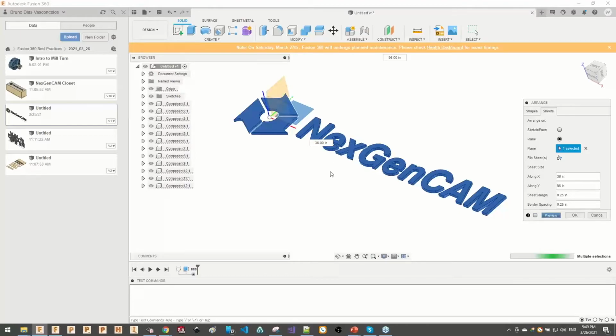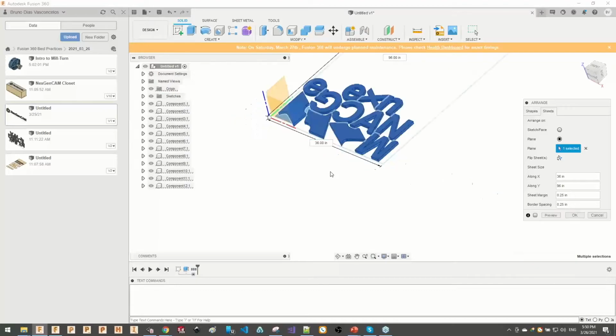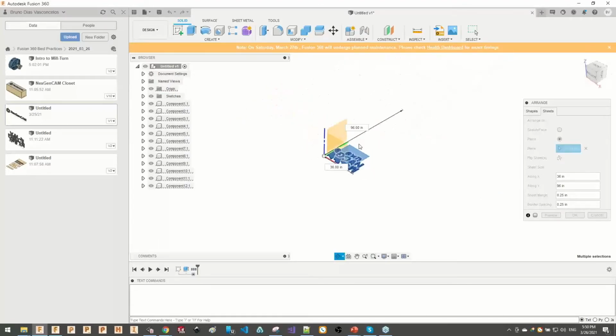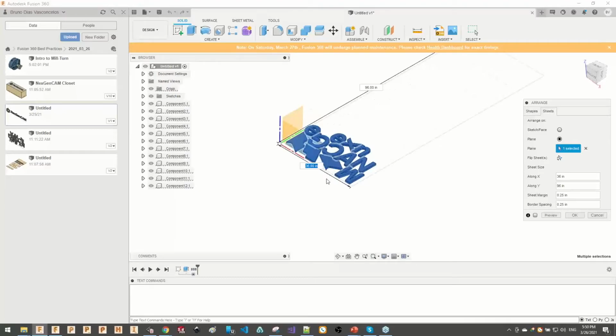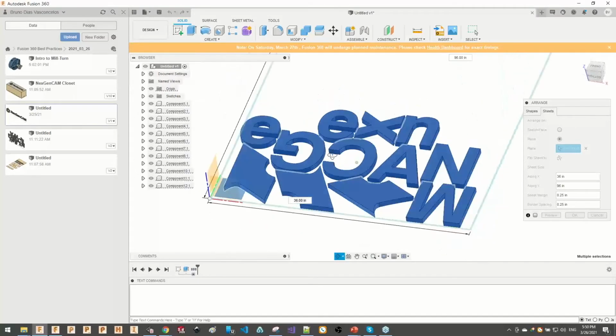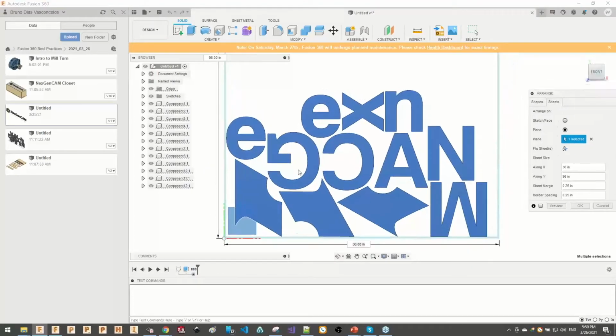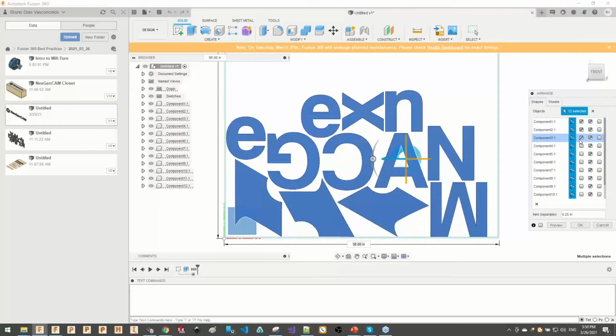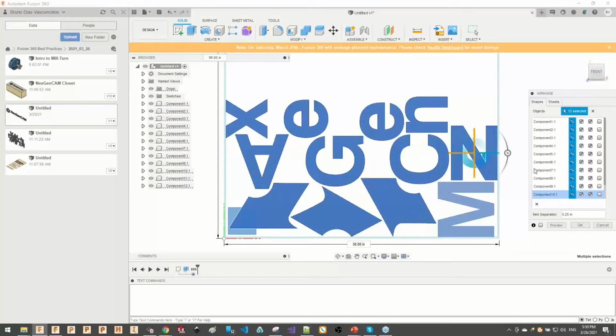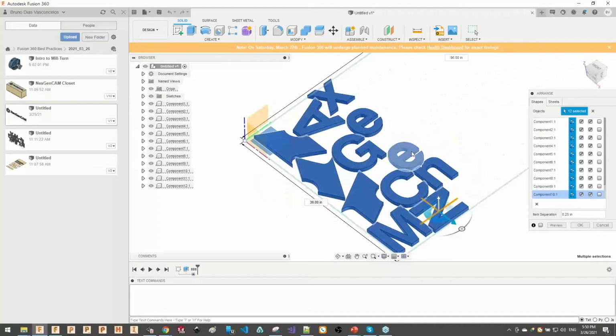Let's say preview. So this is a sheet. There you go. So maybe this part is really small, but here you can see that I told the arrange to rotate the part 180. That's why you're seeing the parts being rotated 180 if it's needed. I could have also allowed it to rotate 90, there is no issue, and recalculate. So now you will have a different solution for the array. You see that? So hopefully you find this useful.